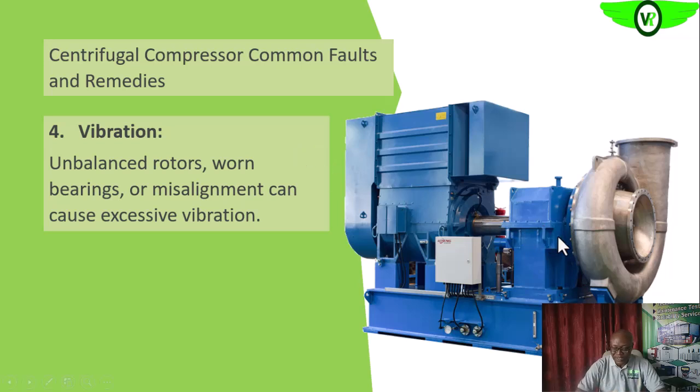Then bearings, okay, at the back of the compressor now, those bearings, the one at the gearbox, front and back, even the one in the motor, all of those can increase the vibration of the unit.